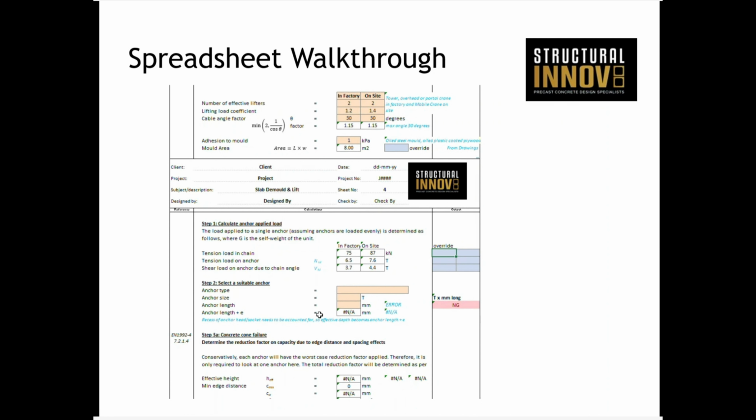So taking that value, from another drop down menu we can select whether it's a lifting pin or a wavy tail socket, and again, the tables from the brochures you can bring into your spreadsheet, digitize them, and make them available here. So if we select a 2.5 anchor, it obviously comes up as not good because we needed 8.7. So 7.5 is still not there. And then we put in 10 and it all gets a green light there.